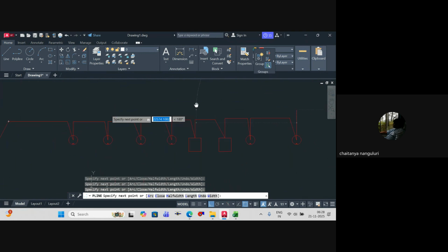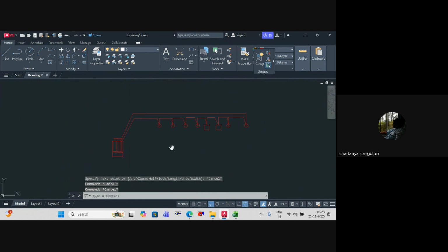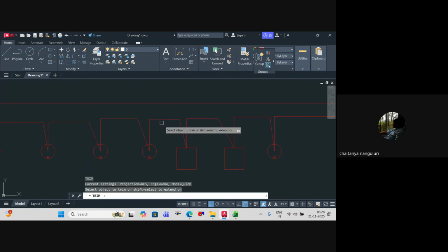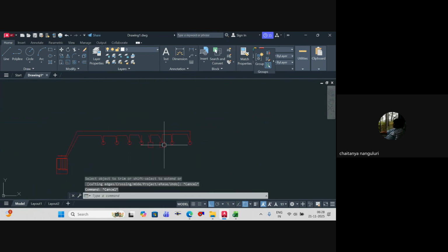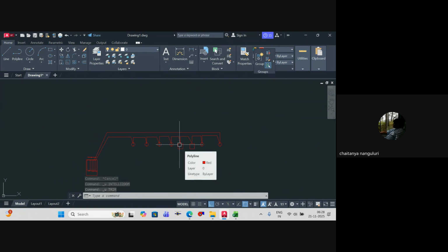But in type B, you basically have your connection back to the fire alarm system again, so that if there's a breakage at one location, even then from here also it is connected, somehow it will work. Understood? Am I clear? So nowadays after looping, again it will come back to your panel. That's how we do it nowadays.